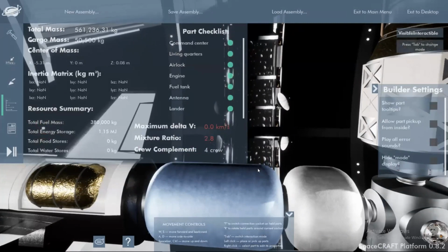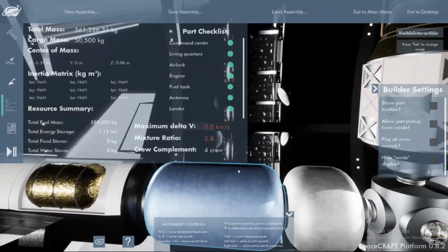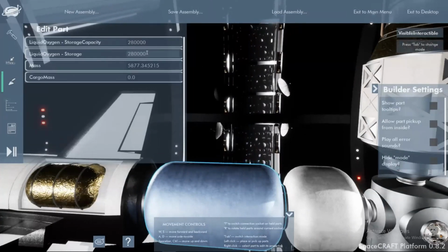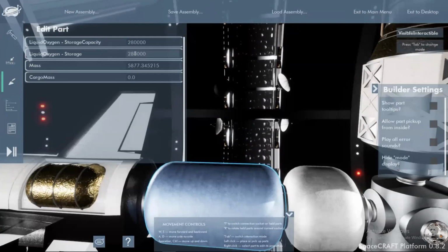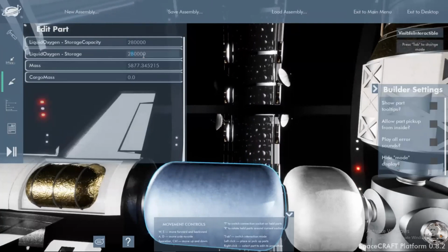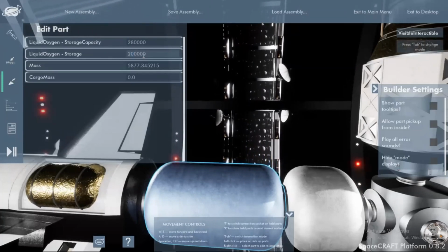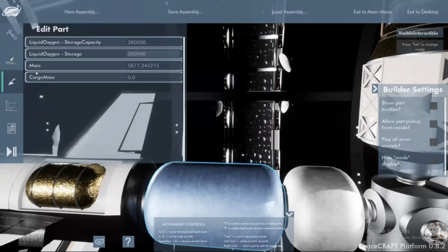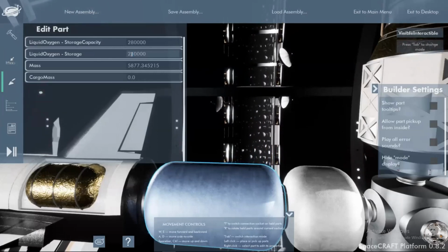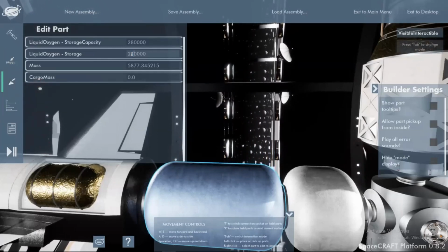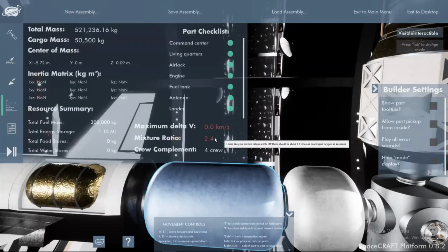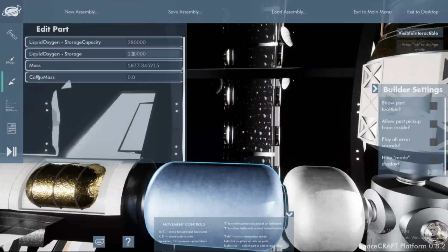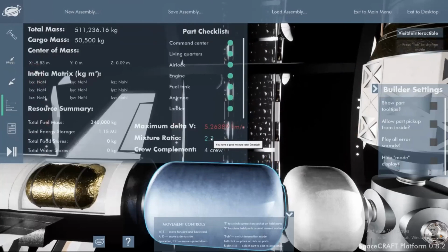So what I'm going to do is right-click the oxygen tank, that's the blue one, and go into this Edit tab, and I can see here the one that's kind of lighter than the others. The lighter ones are the ones you can edit. Let me just lower that to, say, 200,000, hit Enter, and check this. Okay, now we're exactly at 2. Okay, not so good. Let's raise that up to maybe 240,000 rather. Hit Enter. 2.4. Okay, it's a little bit too much. Let's go to exactly maybe 230,000. And there it is. We're perfect.